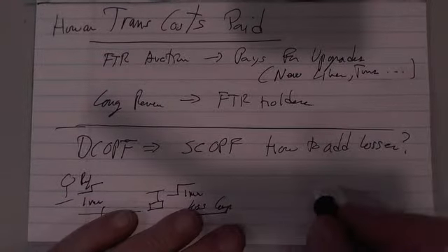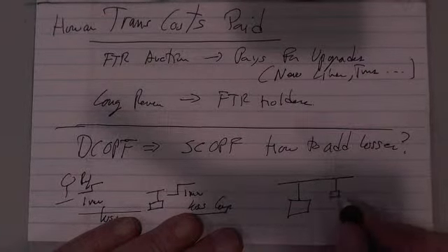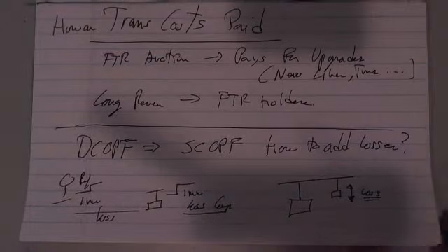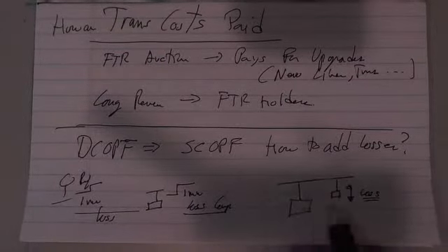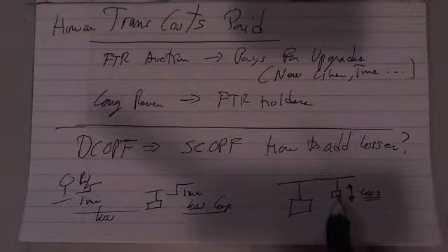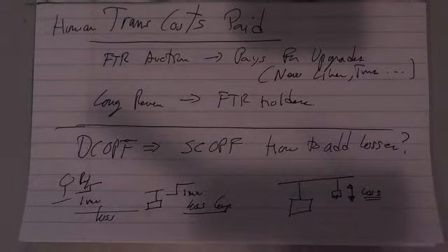Well, really what that is, I've seen people do this before. Here's the load, and here I have this little bitsy load over here that goes up and down, and this is to account for losses, so that this is spread all over the whole system. I put it at a bus, and then they readjust it every once in a while. If the sum of all these on all the load buses equals the total losses of the network, then the total generation will come out, and they've done enough studies to convince themselves that that's an adequate way of doing it without using an ACOPF.